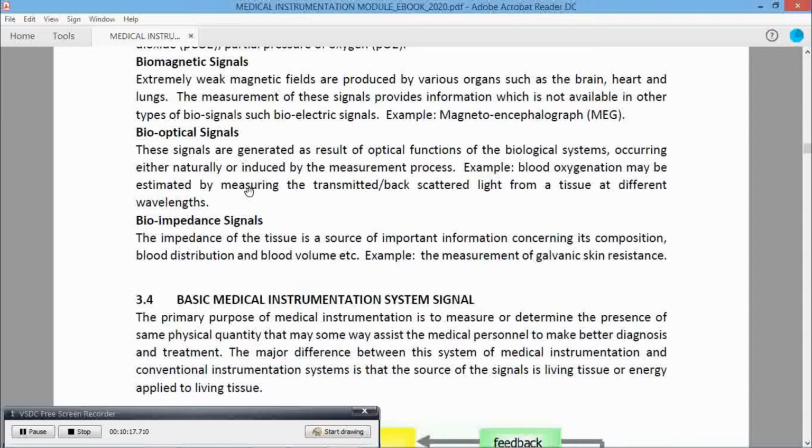If you just want to measure only the pulse, which has nothing to do with oxygen saturation inside the blood, you can use the transmitted light from the tissue, and also the basic LED optical sensors. So if you use optical sensors like LED, you just get the measurement of pulse. But if you go for oxygen saturation, you need to use infrared type of sensors.